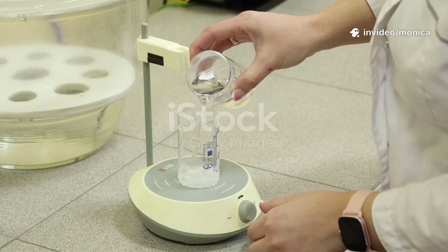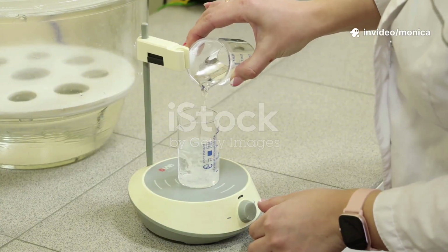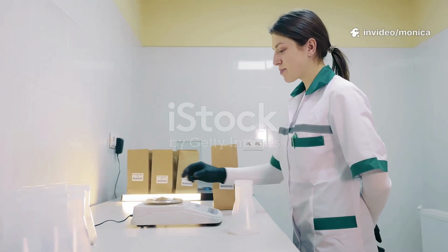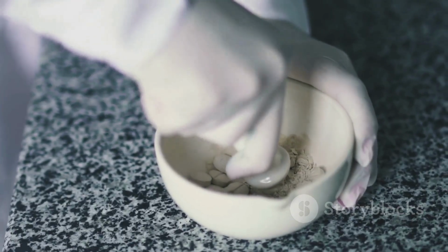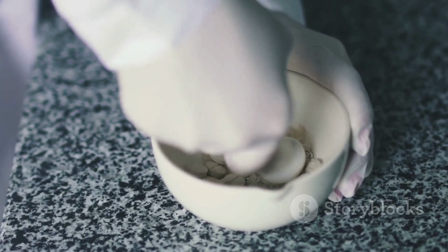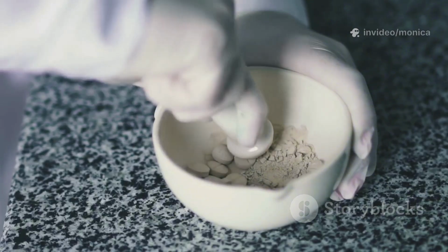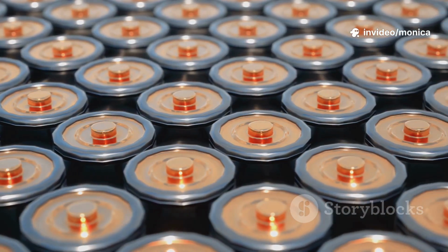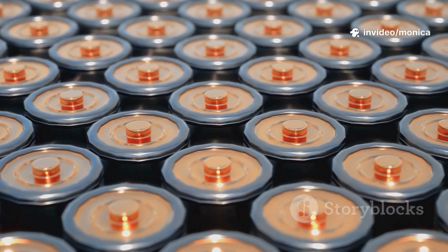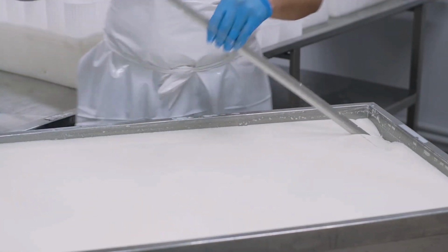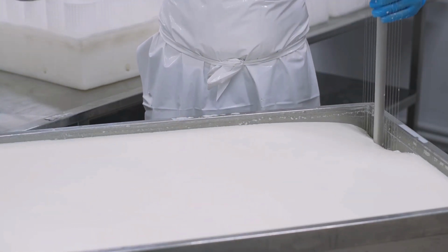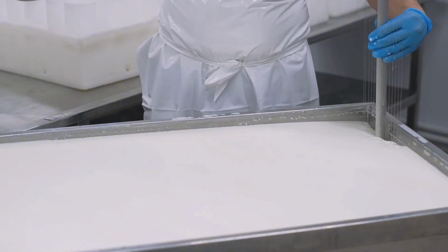So, that's all the nine stages of the lithium-ion battery cell manufacturing process presentation. First is electrode preparation, electrode coating, electrode drying and calendaring, separator preparation, cell assembly, electrolyte filling, cell sealing, formation and testing, quality control, and final packaging.